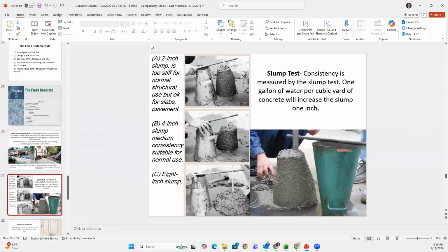One of the indications of good workable concrete is the slump test, the slump ratio. This is the first test that they conduct when you bring concrete to the job site. I will show you a video later on of how a deputy inspector stays on the job, takes samples like this from each truck when they bring the concrete to the job site, puts it in a cone, shakes it, rods it. There's a technique to the madness.